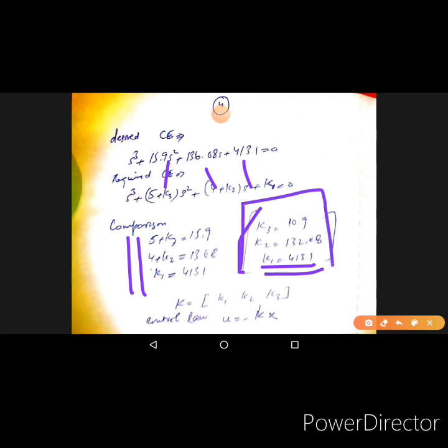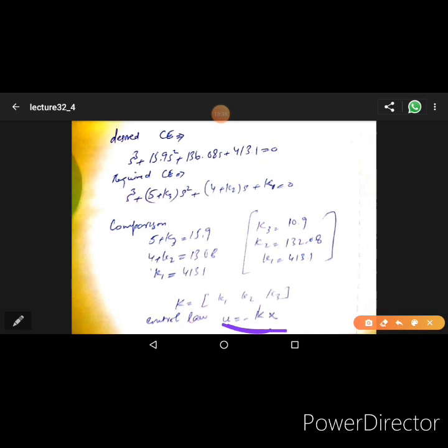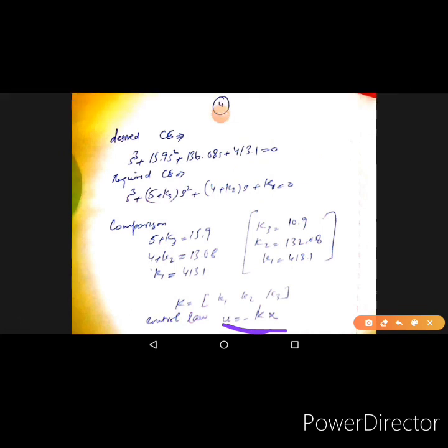K1 K2 K3 ये कैलकुलेट करने होते हैं। फिर आप इसको जो है K1 को x1 के साथ मल्टीप्लाई करते हैं, K2 को x2 के साथ, K3 को x3 के साथ, इन तमाम को जमा करते हैं और u इज इक्वल टू माइनस Kx रख देते हैं। जो u उस प्लांट की इनपुट थी उसकी जगह पे इन तमाम कॉन्स्टेंट्स को करस्पॉन्डिंग x1 x2 x3 से मल्टीप्लाई करा के जमा करके नेगेटिव साइन के साथ इनपुट पे दे देते हैं। तो आप जो है इसके लिए ब्लॉक डायग्राम भी ड्रॉ करें इसका, जिसमें क्लोज लूप सिस्टम का, जिसमें हमने स्टेट वेरिएबल फीडबैक कंट्रोल लगा दिया।